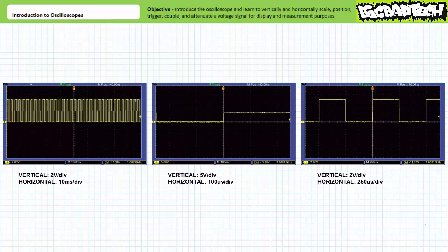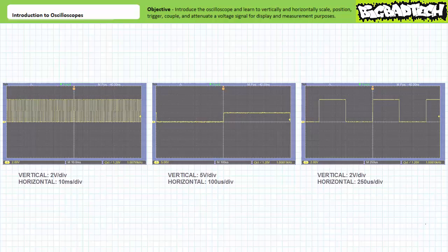Importantly, despite the exaggerated differences, all these pictures are of the same waveform, only they've been zoomed in or out, sometimes to a comical degree, to make a point. The point being the waveform never changes, only the level of magnification does. They're all showing 5-volt pulses at 1 kHz. Under different levels of magnification, the waveform under inspection can and will assume bizarre forms.